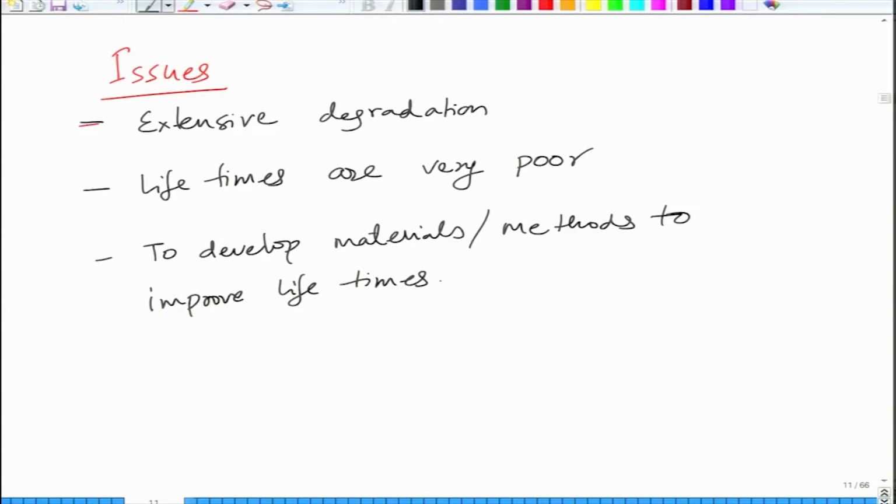So, this is a short review of perovskite solar cells. These materials have shown efficiencies of the order of about 23% as of now. They have certain very good qualities, they have very good light absorption, they are easy to make, they are solid. So, basically this device is solution processable, most of it. Just like organic solar cells, when you make this device, you start from glass substrate, FTO coated glass which is bought from the market, you pattern it,